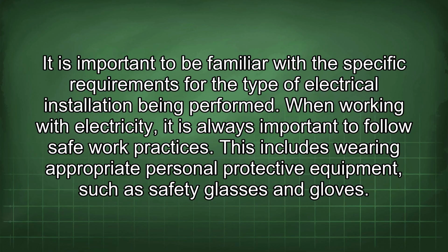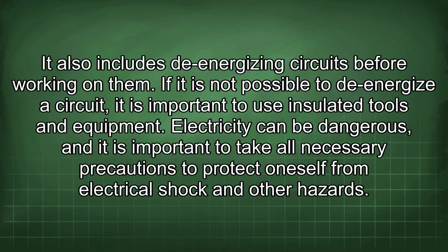When working with electricity, it is always important to follow safe work practices. This includes wearing appropriate personal protective equipment, such as safety glasses and gloves. It also includes de-energizing circuits before working on them. If it is not possible to de-energize a circuit, it is important to use insulated tools and equipment.